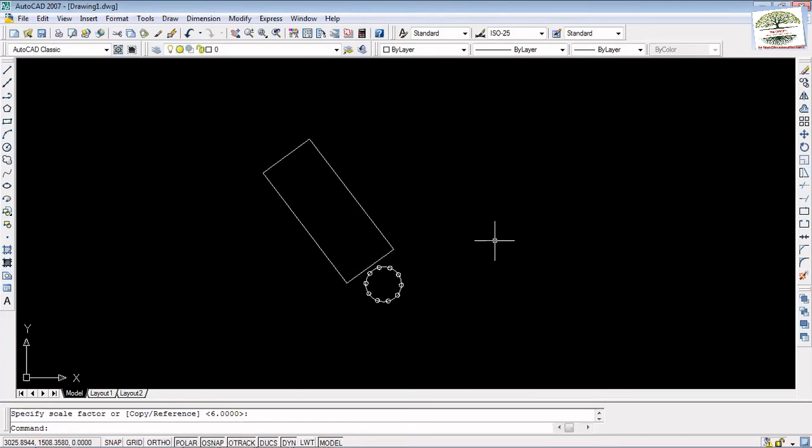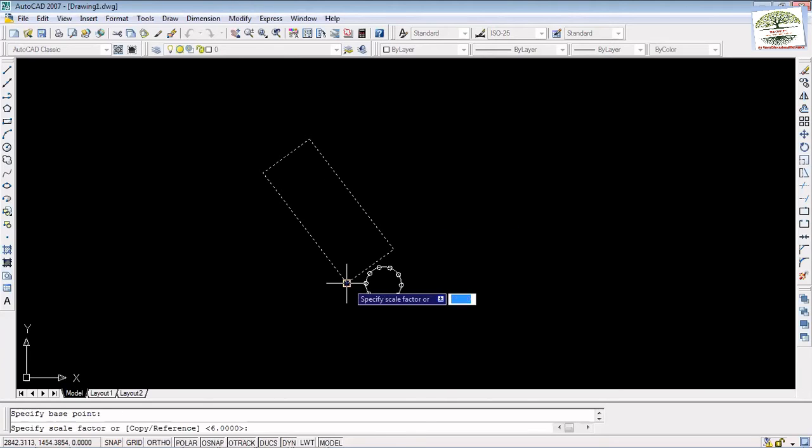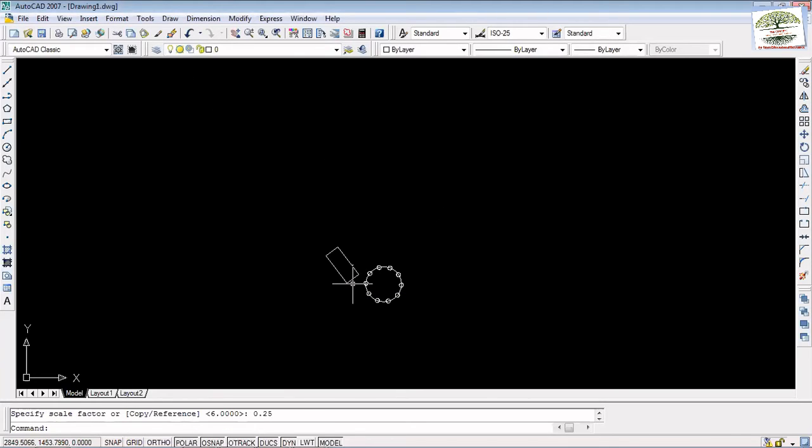And again, I've also told you how, without moving your mouse, you can select it, give the base point, and now just give the scale factor. If you would like to go for 0.25, that means 1/4, 25%. It's a reduction, so you don't have to scroll much. While scrolling the mouse, it's very difficult to maintain the exact scale factor. The perception level is very poor, and accuracy and precision are poor compared to this one. So this is the procedure I usually recommend you to follow.